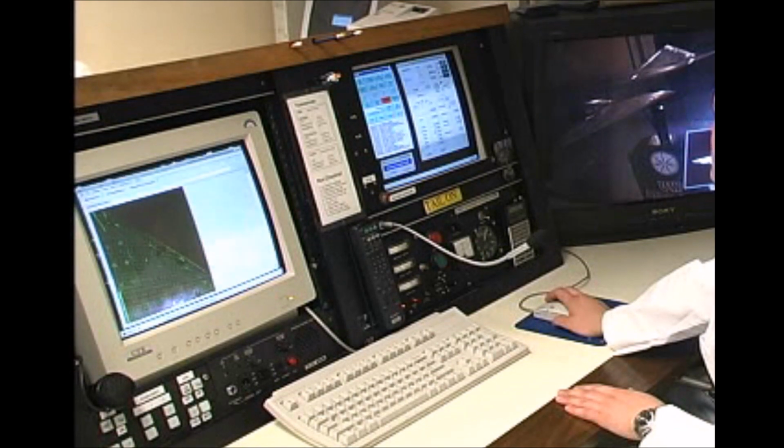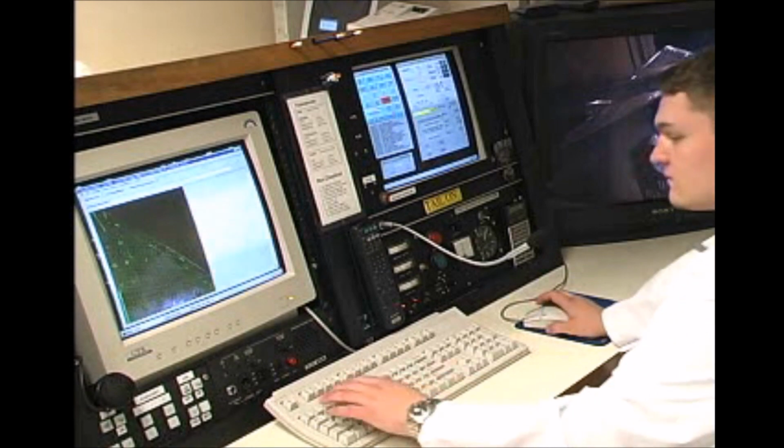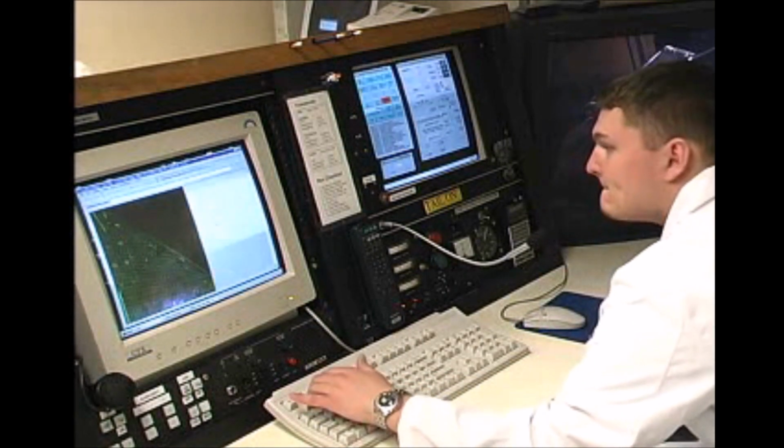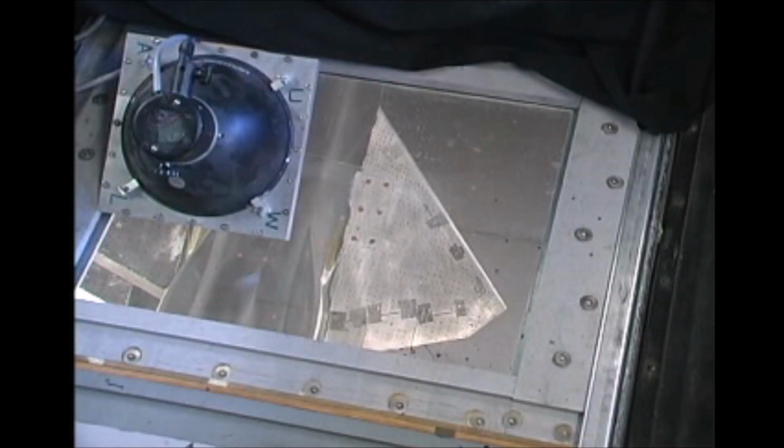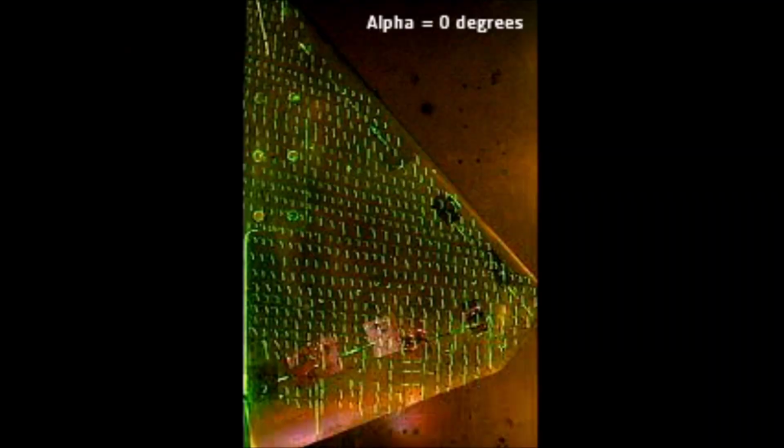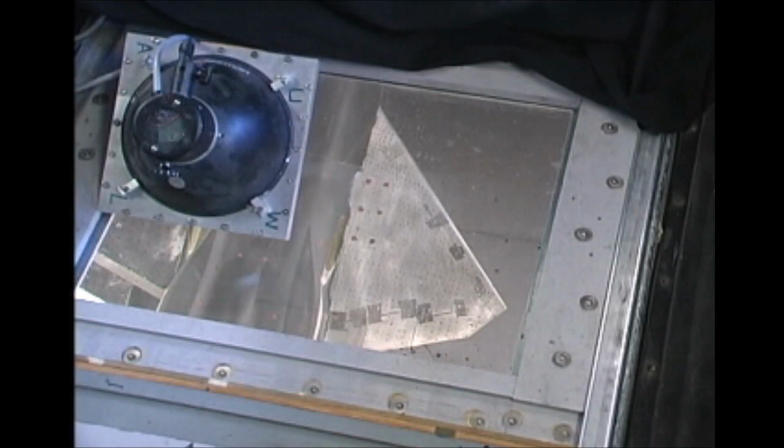These are small filaments of polyester monofilament that are soaked in an ultraviolet dye and then glued to the model surface. When the wind is turned on, the mini tufts move in the direction of the flow, and a UV flash is used to make the tufts visible. This works surprisingly well, but unfortunately it can take a significant amount of time to apply these tufts to the model.